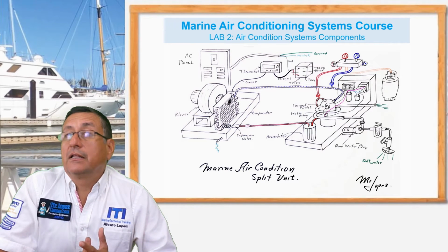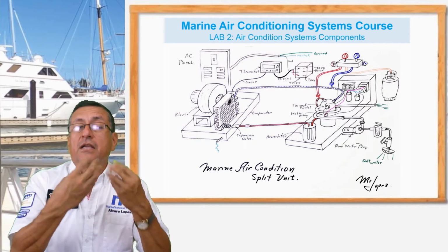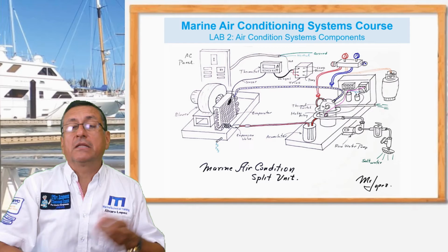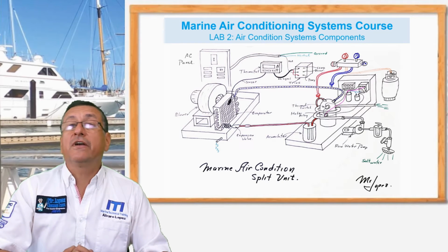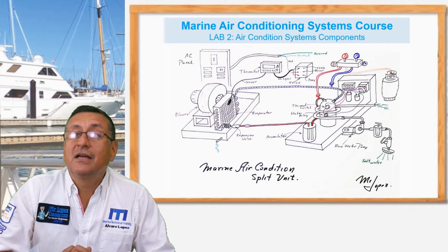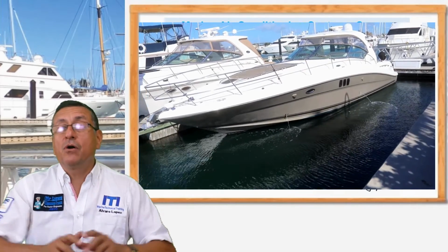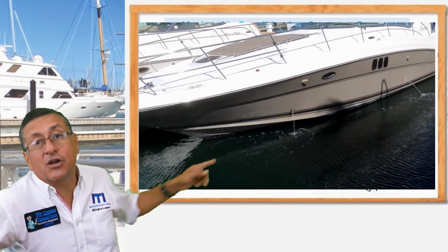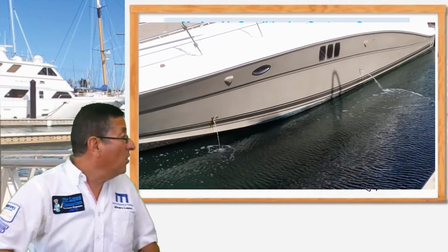And the second one is warm air. Both of them start, but the air is warm. The pressures are okay. The next one is to verify if the cooling in the condenser is good. In my boat, I need to verify if I have water coming out of the discharge. This is an indication that the raw water is circulating. No raw water.